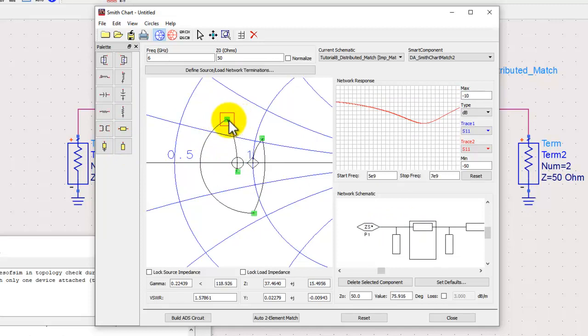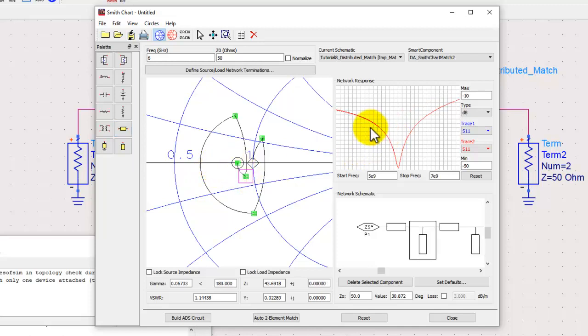Don't directly cross. I could have crossed here, but again you see you will miss the series line point here, and we need to bring it up. So we'll go ahead, increase a little bit, go a little down, and once we are a little down, we will add a series line of 50 ohms so that we hit that line point. And now I have a practically feasible circuit here. All right, so we'll go ahead and build the ADS circuit.